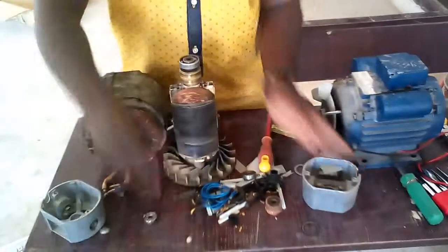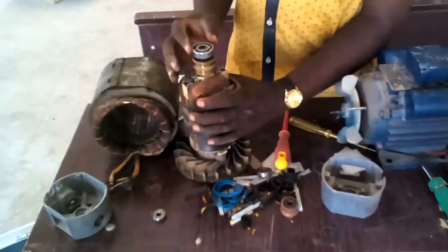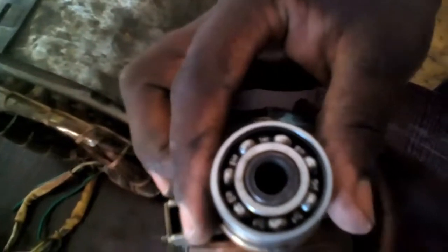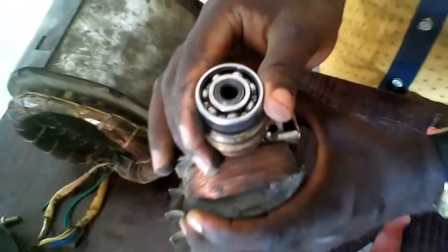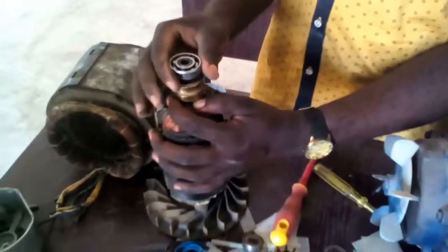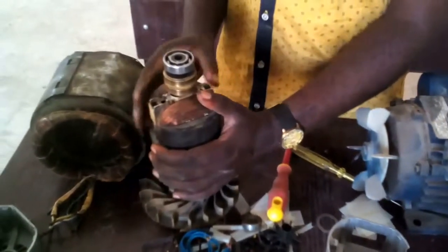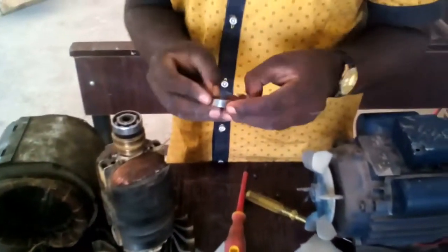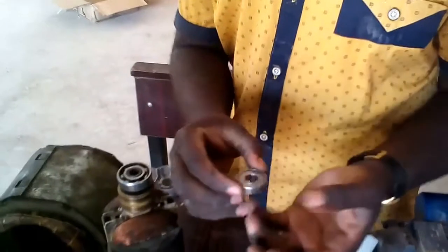Now, what do we do? From physical inspection of the ball bearings, you can easily see if the grease is too much. From this particular bearing, you can see that the grease has actually dried up. So this is most likely to result in overheating of that bearing. But if it is the opposite, supposing the grease is too much, it will also result in excessive overheating of the bearing. Of course, the most likely thing to do is to remove the surplus grease there, wash the bearing and realign.